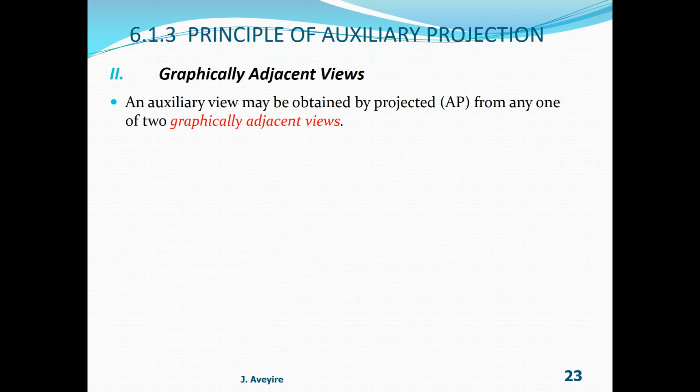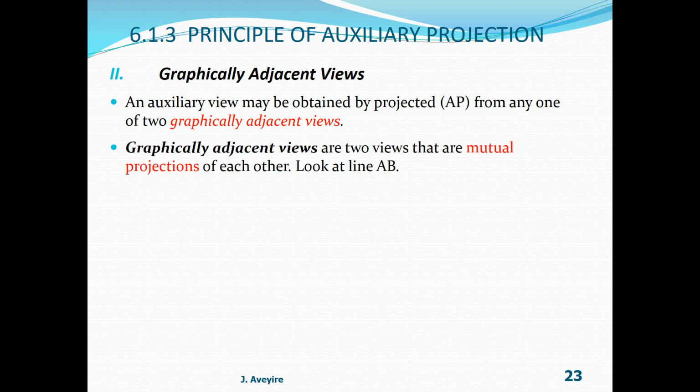Graphically adjacent views. An auxiliary view may be obtained by applying our auxiliary projector from any one of two graphically adjacent views. Graphically adjacent views are two views that are mutual projectors of each other.